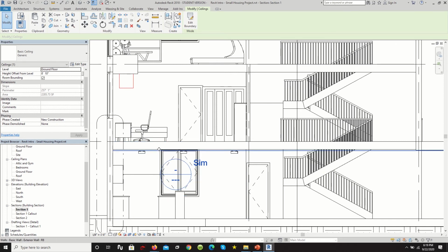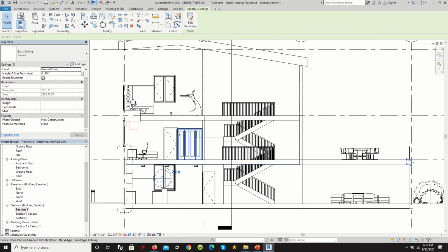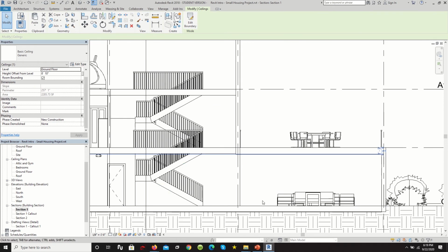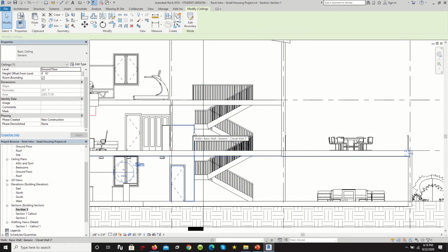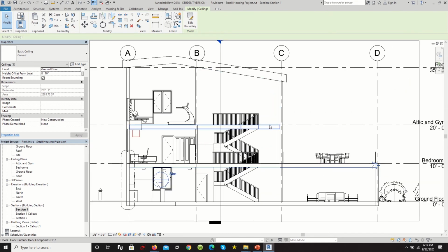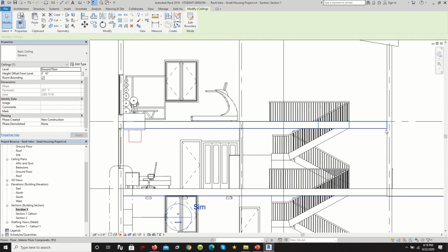And we're going to just repeat those steps on each level, populate it to the best of your abilities, and feel free to add floor lamps, table lamps, whatever you prefer. So I'm going to jump ahead to after I finish specifying all the lighting fixtures. And remember, one more time, for any ceiling hosted light fixture, you're going to have to create the boundaries for the ceiling. You can either draw it or use pick lines if you already have a boundary drawn out.